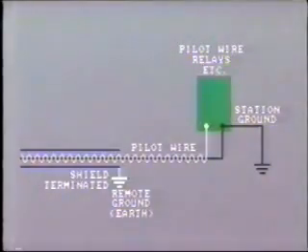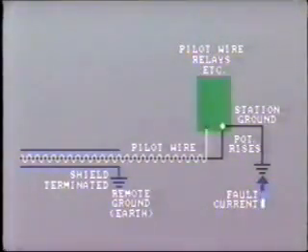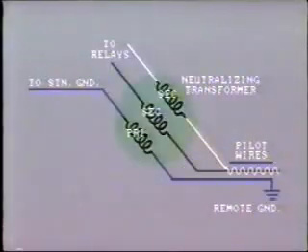Likewise, when grounding the drainage reactors that we just mentioned. However, we still have a problem. When the two pilot wire conductors enter the station, they will be connected to relays which are usually grounded on one side, so one of the pair will be subjected to the rising ground mat potential. The difference in voltage between the two conductors may cause inadvertent tripping of the relays. This problem is resolved by installing a neutralizing transformer, which in effect raises the voltage of both conductors to compensate for the difference.